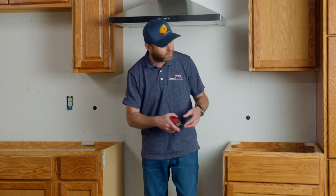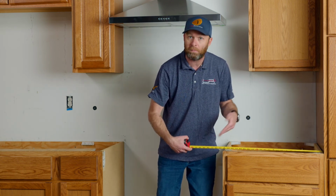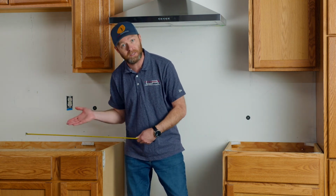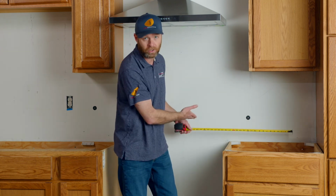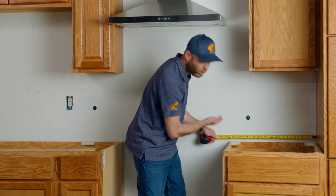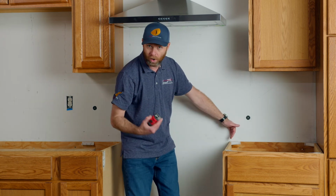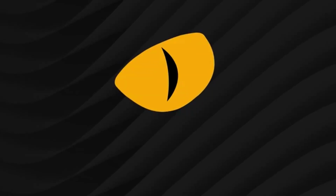So what I can expect when I go to verify the dimension across the front here is I should be overhanging this style by 3/8 of an inch. And then when I verify this dimension, I should be overhanging that style by 3/8 of an inch, splitting that 3/4 in half. Now, when it comes to verifying the back edge of this, what we want to pay attention to is that our laser and what we produce there is bigger than what we physically measure with our tape here. We know that these openings are never perfectly square to each other, so we just worry about the fact our stone, our material covers the panel back here. That's what's most important.